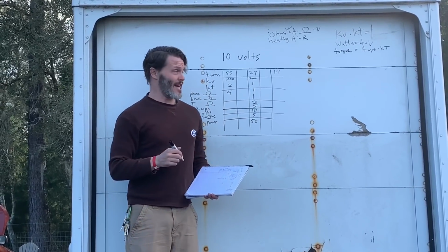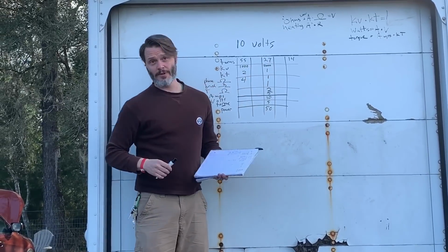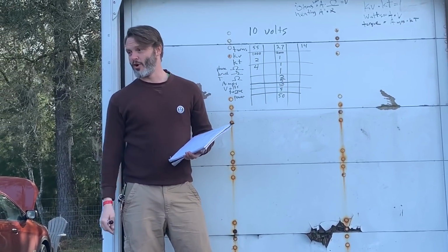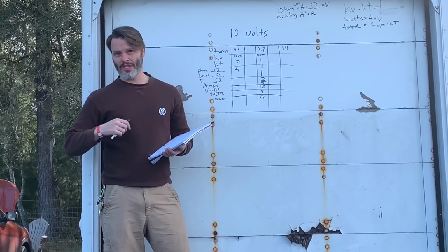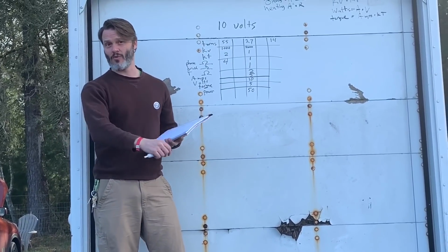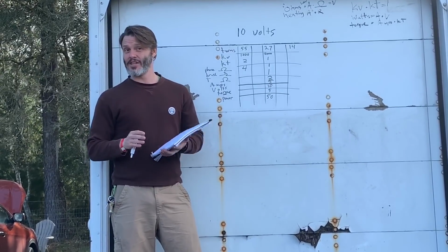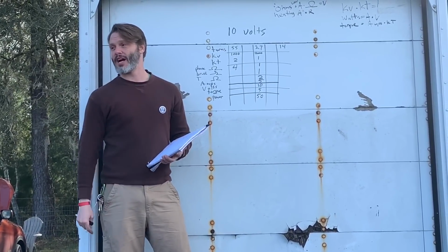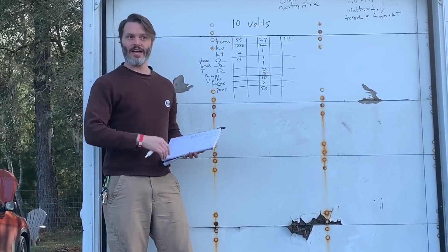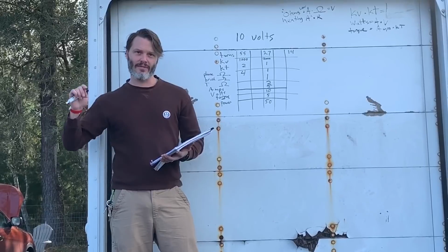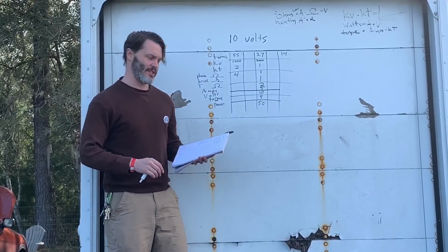The reason why this happens, we've got twice the turns, right? So you would think it's half the wire size. It's going to double in ohms, and that would be correct. But you have twice the turns, you also have twice the length of wire to make those turns. So we have half the size and double the length. Now we are 4 times higher resistance. So that's why it goes in that way. It's not linear. It is actually quadrupling every time you halve your speed.